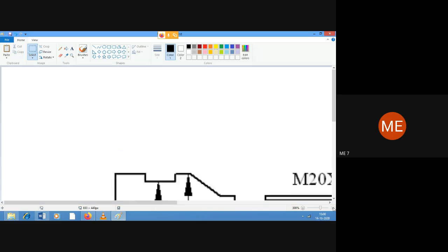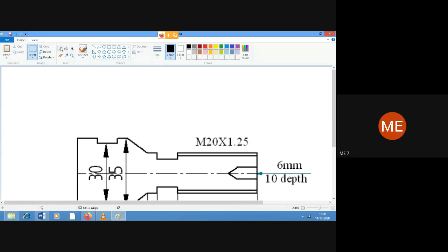So what I want over here is that initially I'll have the grooving tool over here, which will do its machining over here. Option number one is that I can go from here to the home position, then return this tool over here.